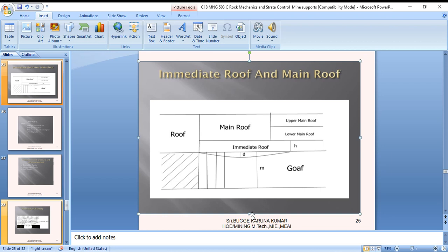The ideal conditions for strata control in a longwall would be, first, that the working place is secured by the support system, which offers enough resistance to prevent degradation of the roof, falls, cracking and blocky areas within the working zone. Second, overlying roof rocks fall as soon as the last row of supports is withdrawn, filling the goaf completely. The first condition is sought to be fulfilled by proper support density, such as to limit convergence to a tolerable level.